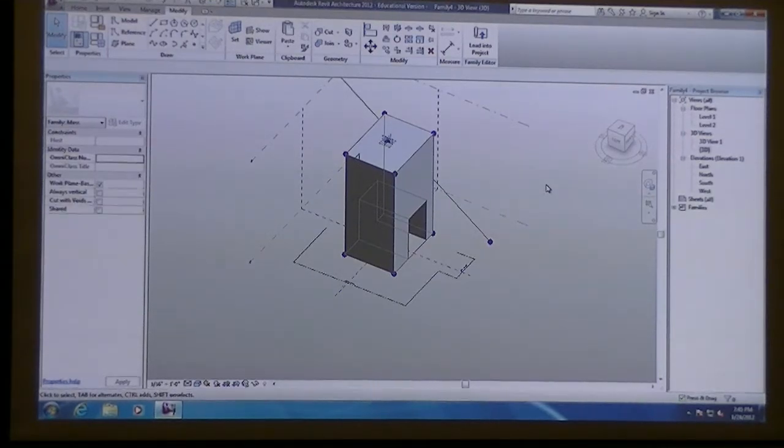So just the same methods that we've worked with, you might have each of these, like for instance, I would make a wall, this wall that's at the end of the bridge, I'd make that as one component that has a void in it, because then I can place it again on the other side when I'm putting my compilation model together, and it'd be the same piece that I could also change parametrically as well. Same thing with the bridge component, and then this platform, if you have a tower or on my bridge, I've got kind of this, hard to see, but this observation deck that goes down and it's connected up to this top portion of the bridge.